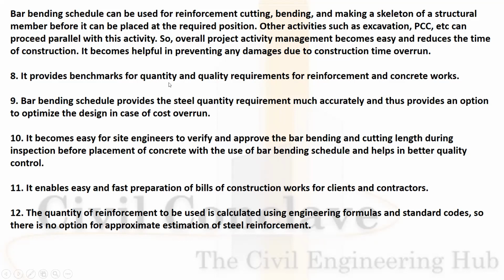It provides a benchmark for quality and quantity requirement for reinforcement and the concreting work. Bar bending schedule provides the steel quantity requirement much more accurately and thus provides an option to optimize the design in case of cost overrun. It becomes easier for a site engineer to verify and approve the bar bending schedule during the inspection before placement.